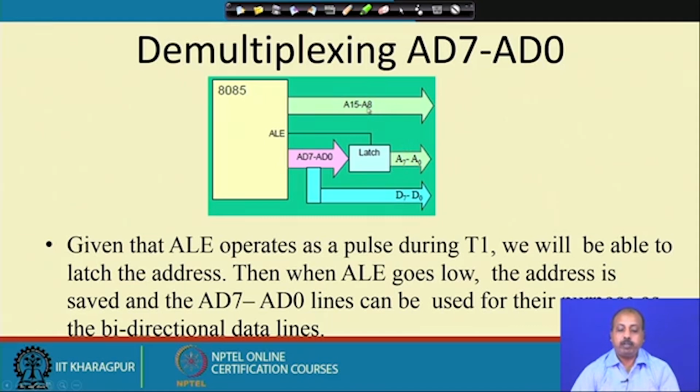So, A8 to A15 is there for 3 clock cycles, and A0 to A7 is also there for 3 clock cycles. Now the memory, getting the 16 bit address, can generate the memory location content on D7 to D0, and it will be connected to the data bus line. Or if the processor is trying to write something, it can put the values of D0 to D7 onto these multiplexed pins, but ALE is not generated. So, it will be available on D0 to D7.